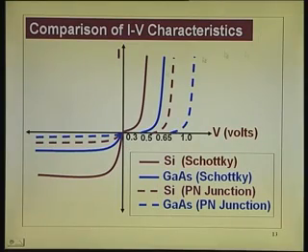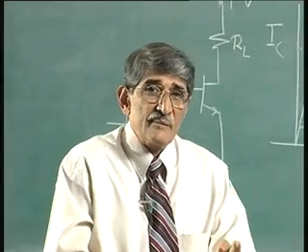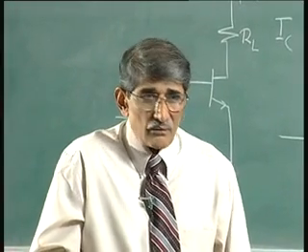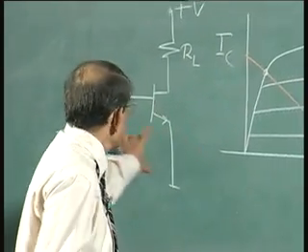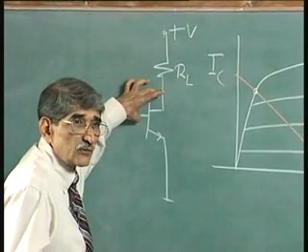If the junction is going to saturation, that is conducting, you will be somewhere here. Now, I do not want the transistor to go into deep saturation. When you say deep saturation, the forward voltage across the transistor's collector base junction is large, almost close to the emitter base junction voltage, which is 0.7. So, this may be 0.7, this may be 0.6, and it goes to that.